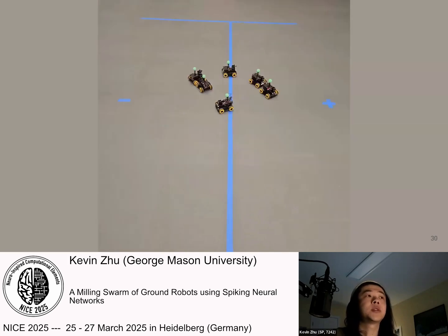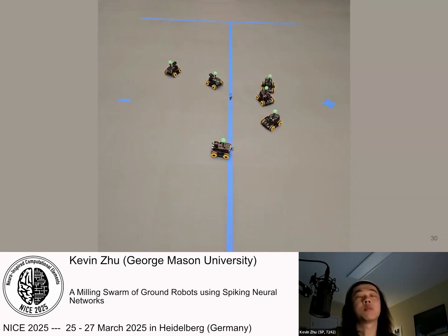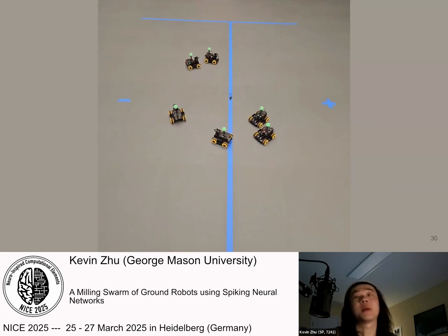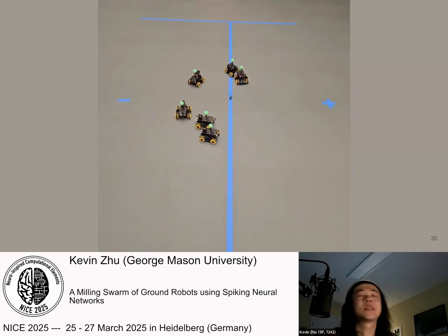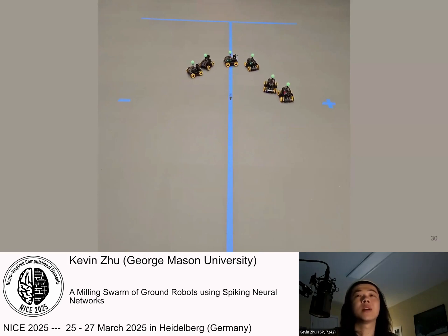So a simpler solution to this was to just remove all of those lower wheel speeds, because the robot inconsistently moves at those anyways. Remember, this is open loop. And this was the less than ideal result. The robots are only allowed to move either full speed forwards, full speed backwards, or 0 for the forward speed. And for our turning rate, we allowed left, full speed, or right, or 0. And the results are what you saw here. We still don't quite get this sim-to-real transfer. But we had one more trick up our sleeve.